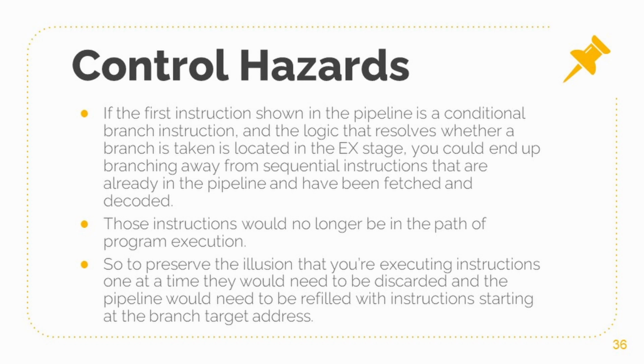In speculative execution, the CPU proceeds to execute instructions speculatively along the predicted branch path, even before the actual branch outcome is known. Instructions are executed out of order, and the CPU maintains a reorder buffer to ensure that the results are committed to architectural state in program order. If the prediction turns out to be incorrect, the speculatively executed instructions are discarded, and the correct path is followed instead. By using branch prediction and speculative execution, the CPU can minimize the impact of control hazards and maintain efficient pipeline operation.